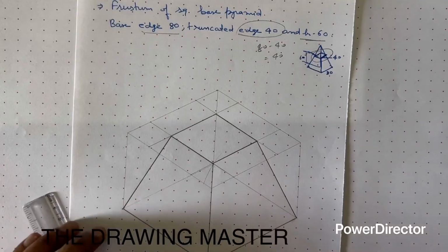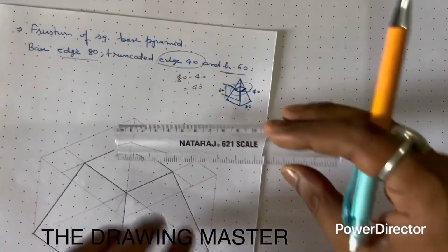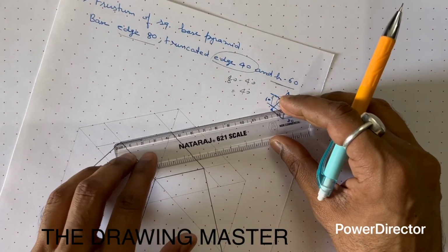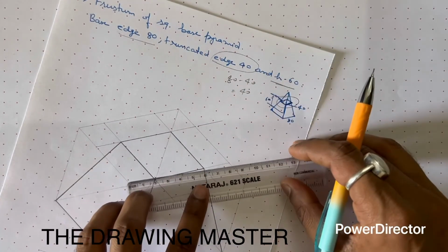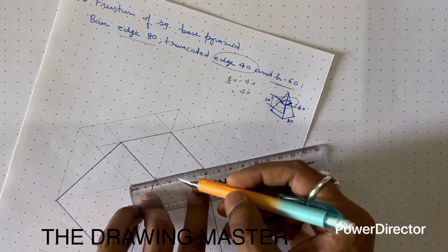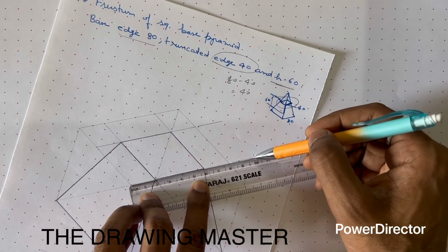Let's see the dimensions now, how to write the dimensions. We'll write 3 dimensions here. First, take the extension line from this truncated edge. Just remember, here you have to use the 30-degree lines for dimensioning also. Just align your scale with this line because this is already at 30-degree.